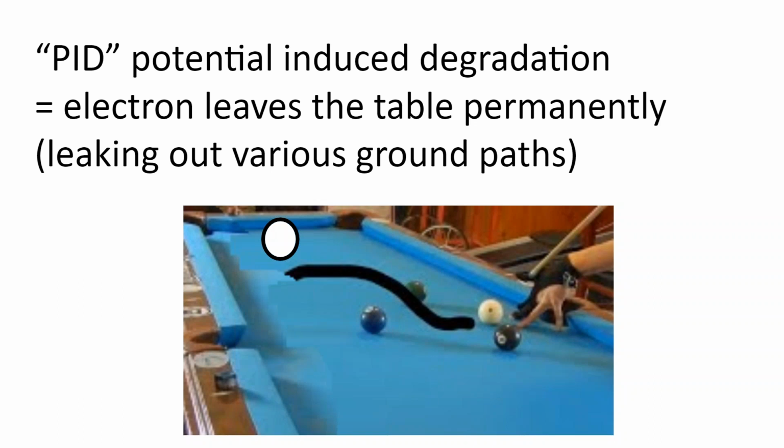generally when that happens, there's a gap in the panel where there's not supposed to be one, and slowly but surely molecules of water from humidity work their way in and start pushing the panel up from the silicon, ultimately corroding the environmental seal of the panel. But often it might be an electrical fault in the panel itself that causes that unzipping, if you will. And so an electrical fault inside the panel could lead to a gap that accelerates the fault to the edge of the panel, and we'll see what that looks like in a minute.